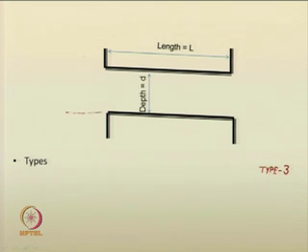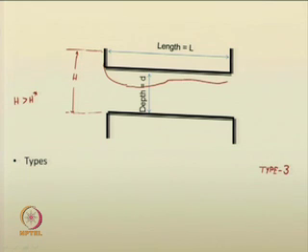Here, although you have headwater depth h like this, h is greater than the critical value, still the flow inside becomes like this. It will gush like this, then it will flow like this, then in the outlet it will come and drop to y t.